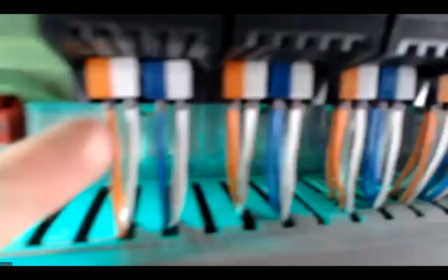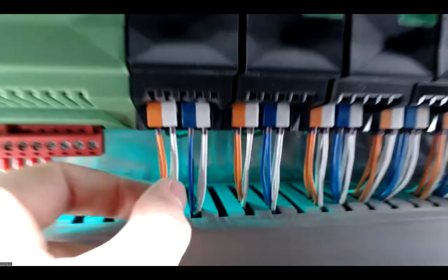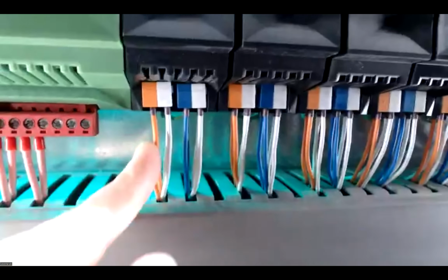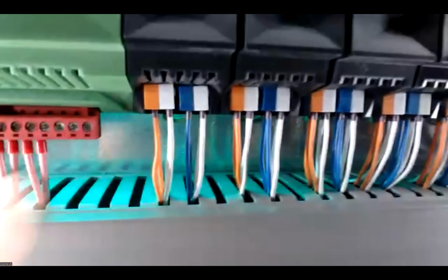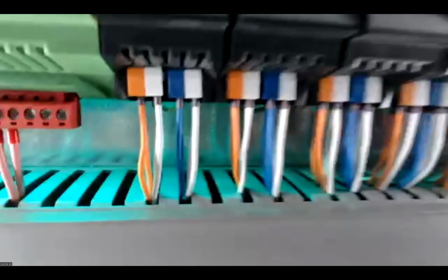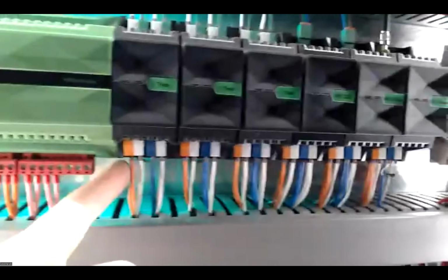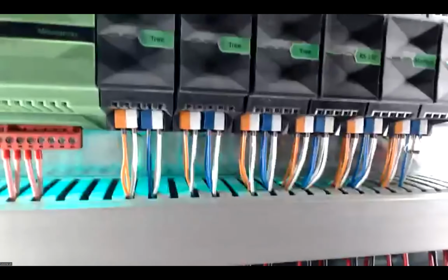As you can see, these cables also have ferrules on them, but that is a solid core cable. So we actually don't need to have a ferrule on it. We can just go directly into the pushing connector, and that is going to be better for the device, better for the connector, and overall, we don't necessarily need to spend time putting ferrules on everything that we want.